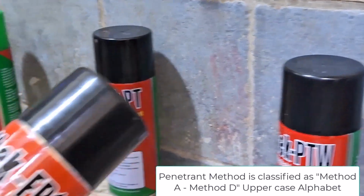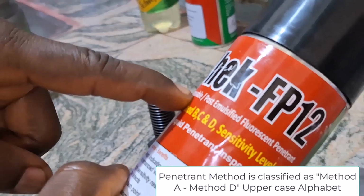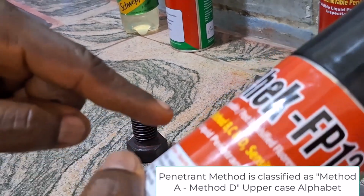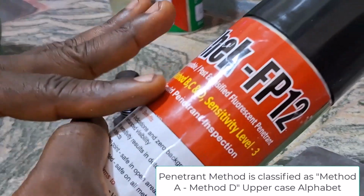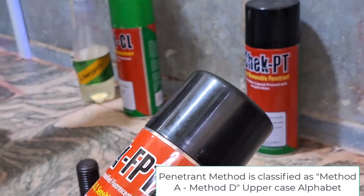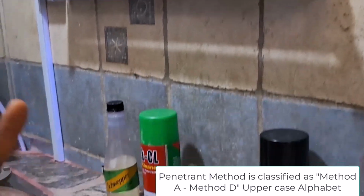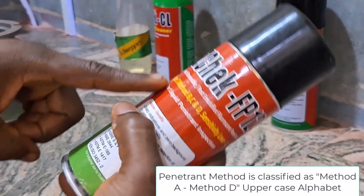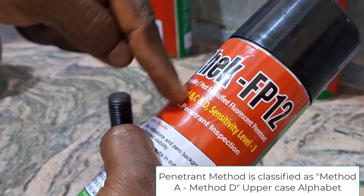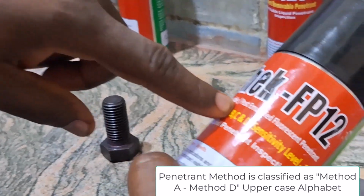If you look at this third one now, it's a solvent-removable, which is type C, and also post-emulsified fluorescent. Because it is fluorescent, our viewing condition is no longer visible light, but we're going to be using UV light for viewing. So that makes this type 1. The type 1 can apply to method B, C, and D. Method B is post-emulsified lipophilic.